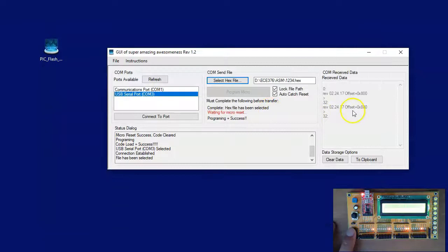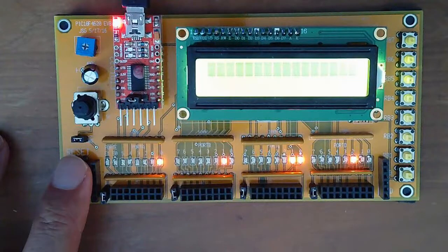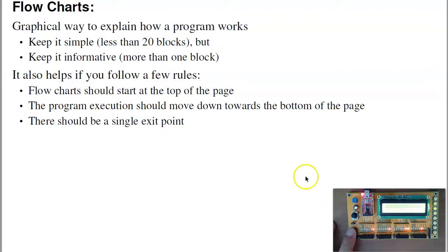Pick that file. When I hit reset, I'll get that 321 message. On 2, it cleared out the old program, waiting for a new one. Hit program, and there it is. Here I've got a equals 1, b equals 2, c equals 3, d equals 4. So that's all you need to do to download your program. And the nice thing is if I want to change the program, I just change, recompile, download. Very easy to download a program.